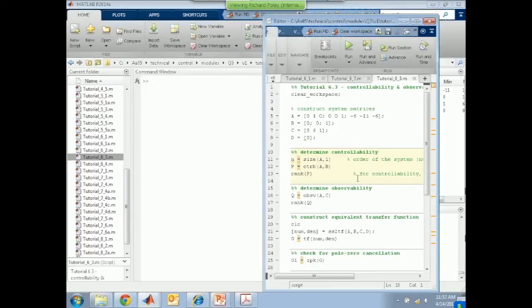And now we're going to determine, firstly, controllability using exactly the same technique as before. Construct the controllability matrix and determine whether its rank is equal to the size of the system matrix. If it is, then the system is controllable, and if it's not, well, it's uncontrollable, but happily this one is, because the system matrix is 3 by 3. This is the P matrix. We're looking for the largest non-zero determinant in that, and it happens that this does actually have a non-zero determinant, so therefore the rank of this matrix is 3. 3 equals 3, and therefore this is a controllable system.